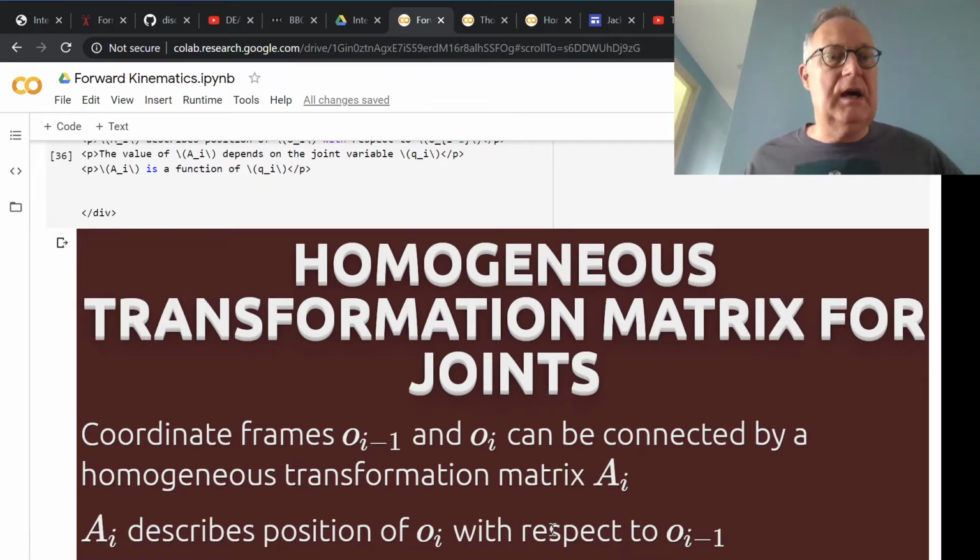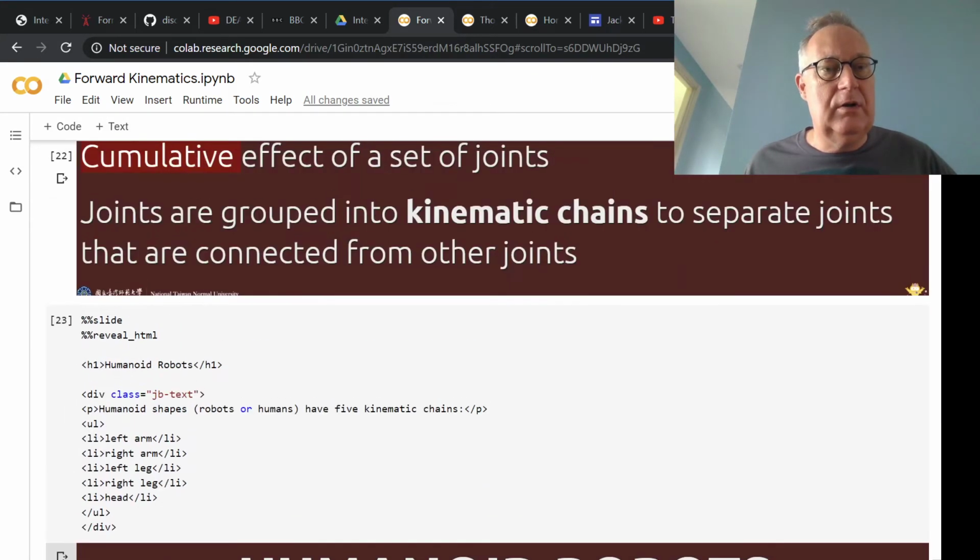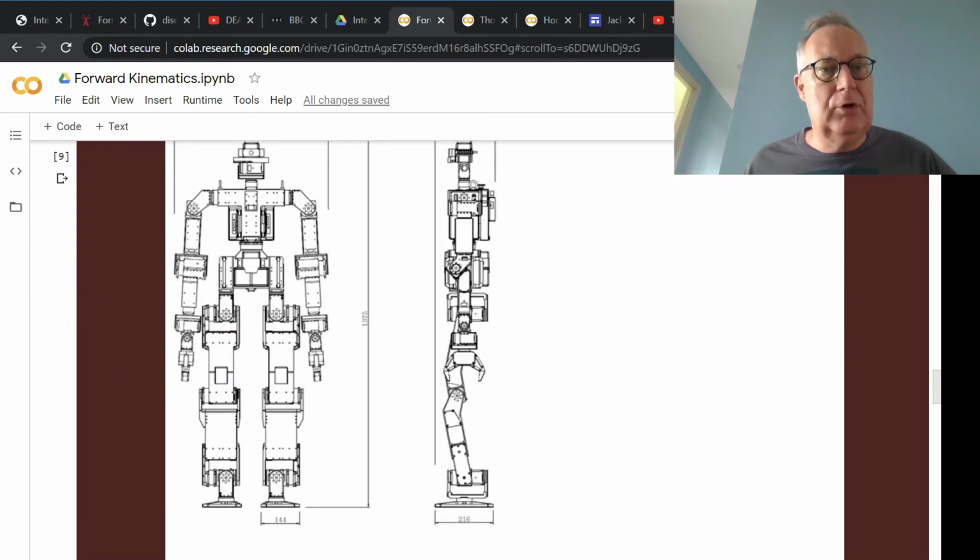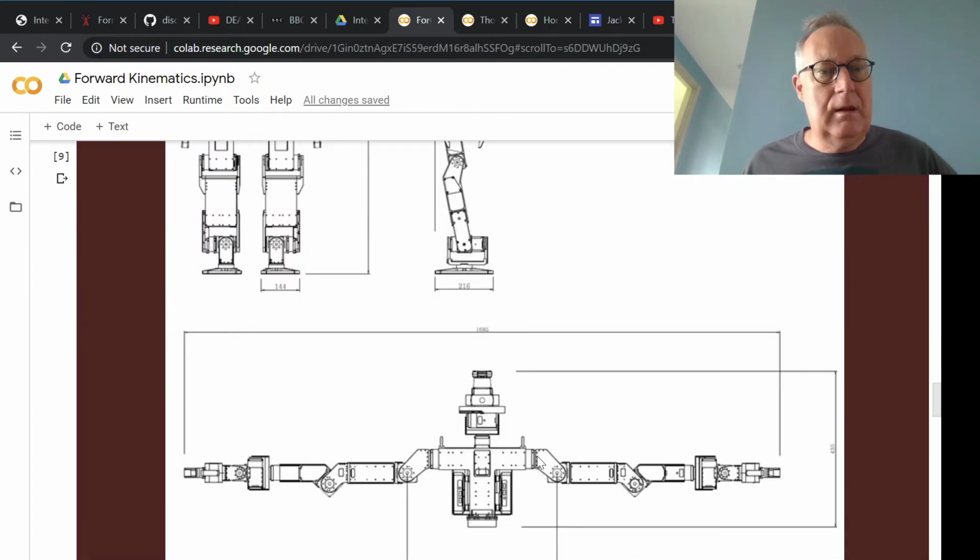However, right now that just means that for each one of my motors here, I have matrix A1, A2, A3, A4, right? But they are only the relationship between the previous link and the next link. So A4 will only model the transformation from link 3 to link 4, to the end effector, for example.